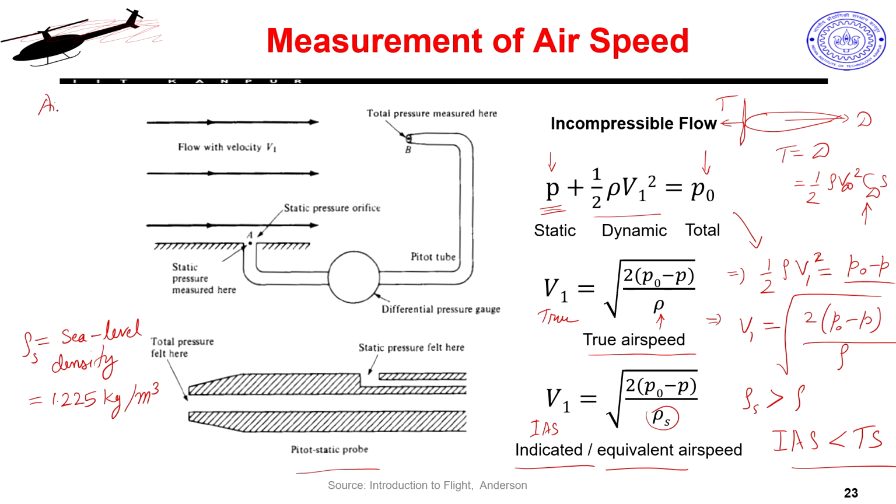Why? Because my airspeed determines my lift and drag values, and if my lift comes below my weight, my airplane will stall, means it is no longer able to support its weight, it will start descending, falling, whatever. So, I must actually maintain my airspeed above my stalling speed, right. So, what I am saying is that it should be greater than,